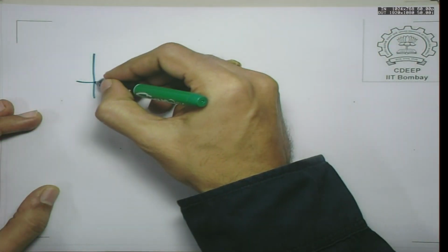One point which we should also remember is many of these instruments, like this digital storage oscilloscope, are based on sampling the waveforms and then plotting them. You should choose the sampling frequency high enough. If your sampling frequency is not high enough, you may end up with another spurious kind of effect called aliasing. For example, if you are measuring a sinusoid which is of